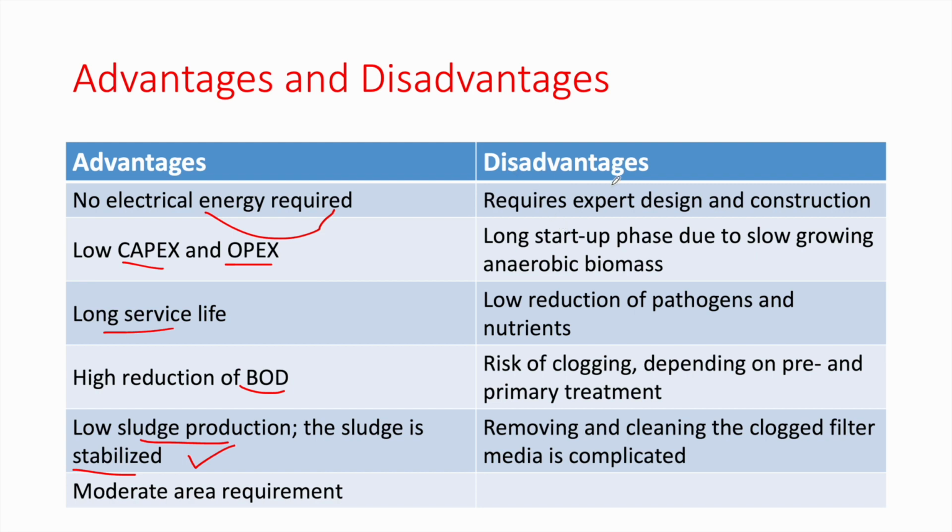Disadvantages: it might require expert design and construction. Also, we have a long startup phase due to slow growing of the anaerobic biomass. Like any other anaerobic system, the startup phase or the formation of the biomass can take 6, 7, or even 8 months. So it is pretty long. It's a pretty long startup before we see results.